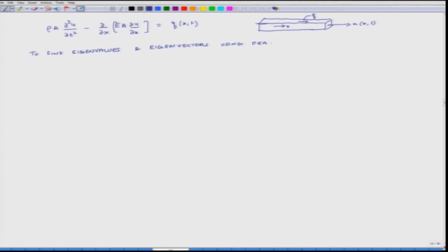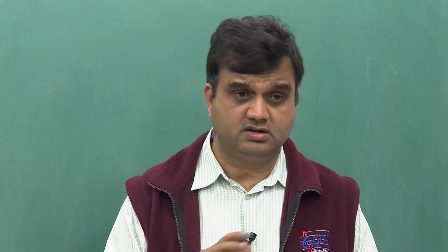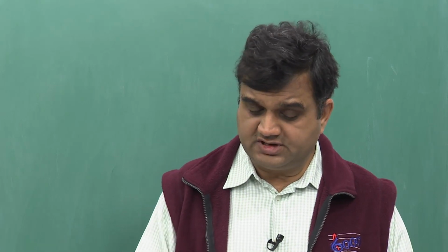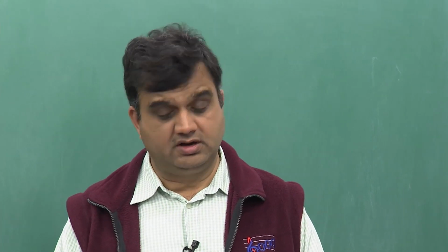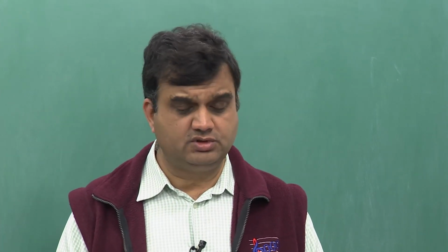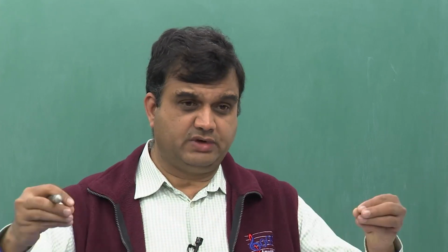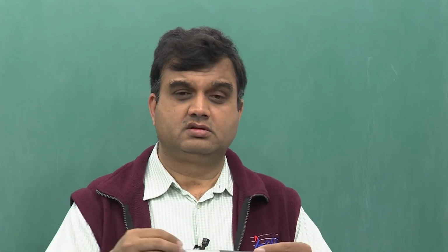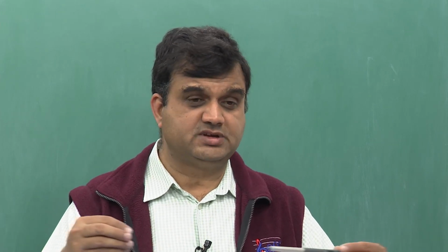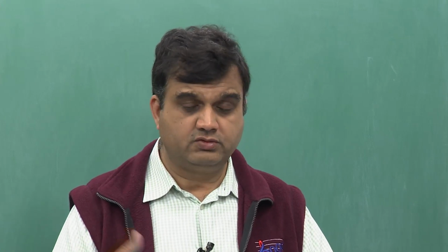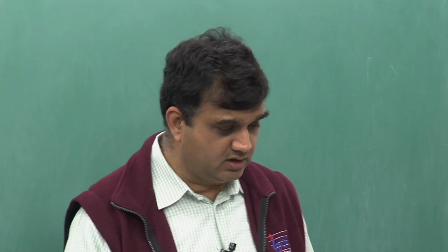Okay. Now, our first step is, so this is a second order partial differential equation. It is second order both in time and in space. So, the first thing we do is we try to convert this into a second order ordinary differential equation, and we do that by realizing that if the bar is vibrating on its own, it will have some sort of a harmonic motion with some natural frequency omega, right.